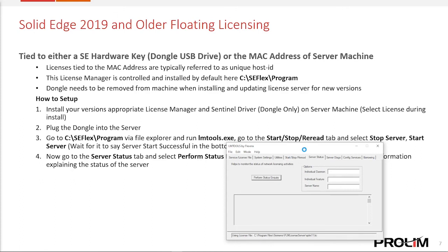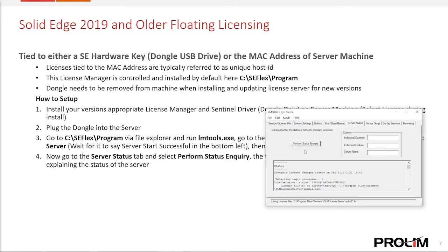Now what this is going to tell us is all the information about the license manager that we need to know about how it's running, is it up and running correctly? And the two things we need to look for here are license server up, vendor daemon on. As long as we know these two things, we know the license server is up and running, and we know the vendor daemon is currently on, so that we know the licenses are being distributed.